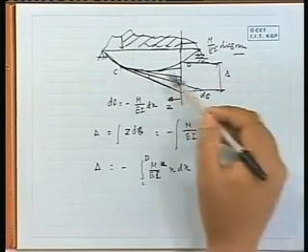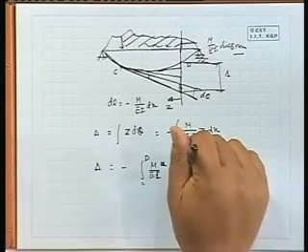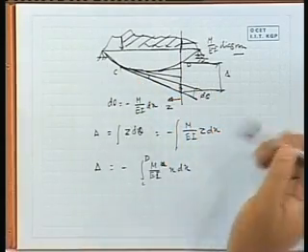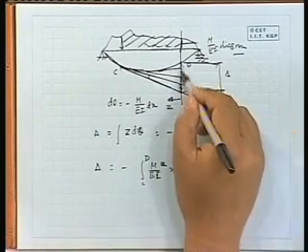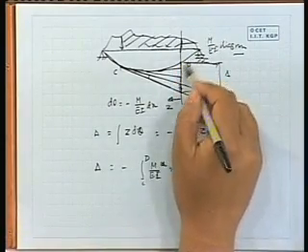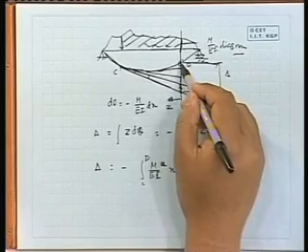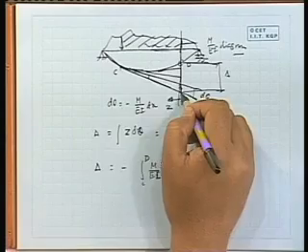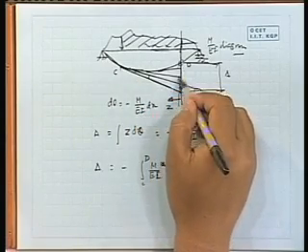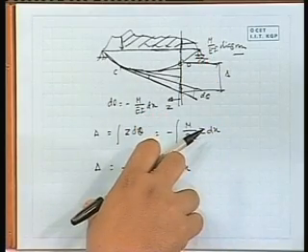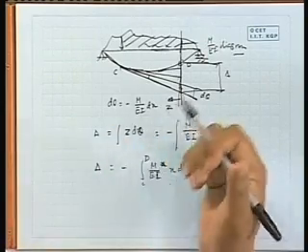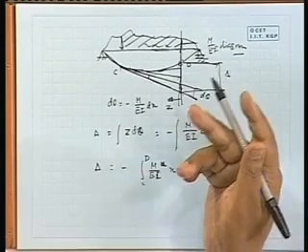So, if you take any 2 points and if you calculate the first moment of area under that curve from C to D about D, so we will get this value. This value is what? From the deflected curve D, if we come down perpendicular to the original line, it will meet the tangent drawn at C. So, whatever distance you will get, that can be calculated from here. Okay. So, this is the second step of our moment area theorem. So, it has 2 steps.